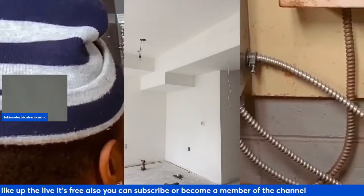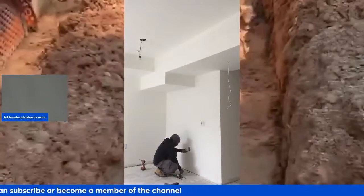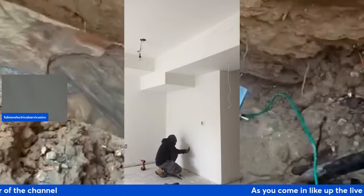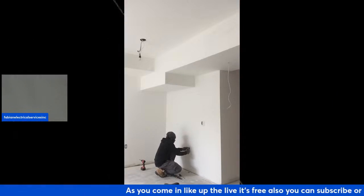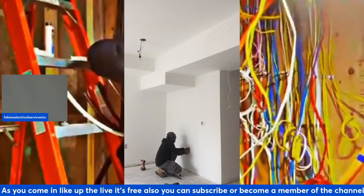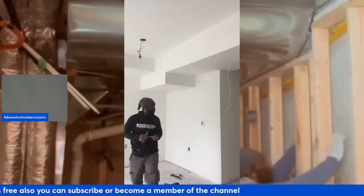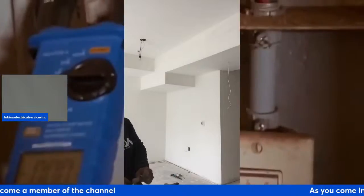Also, a lot of times people will install the receptacles but will not take into account the TV itself. Most of the time, it's better to have the TV on its own, but if it's not on its own, you can, as long as you have that whole circuit with an arc fault.